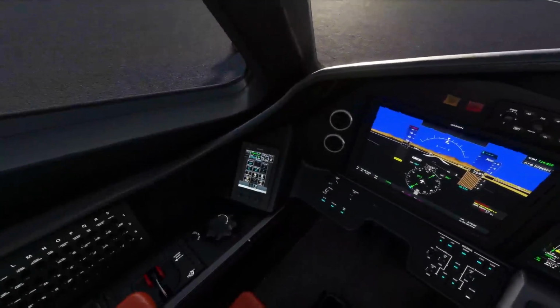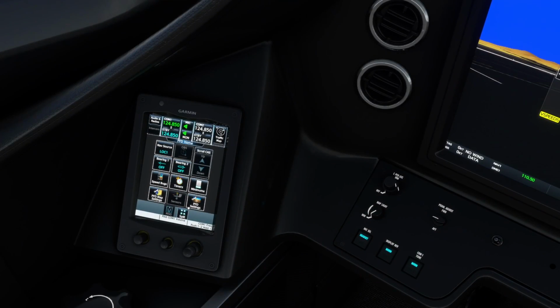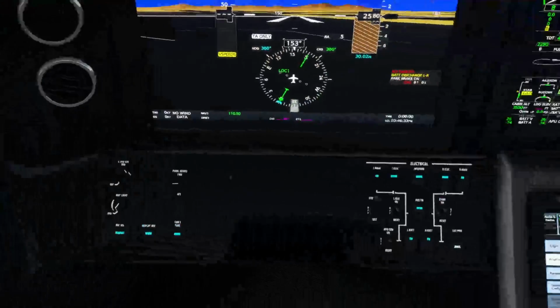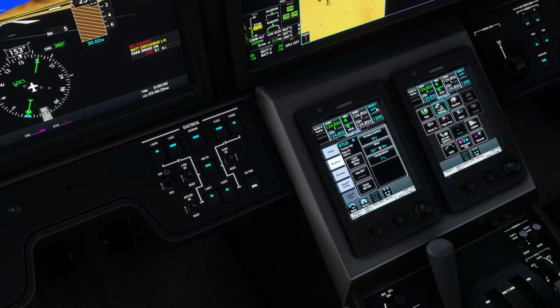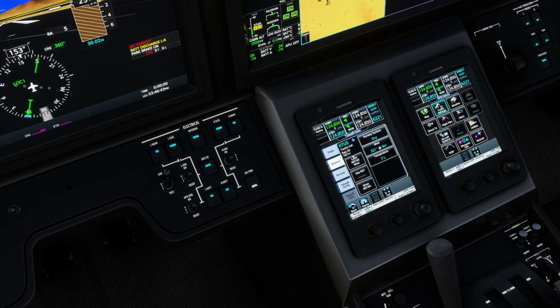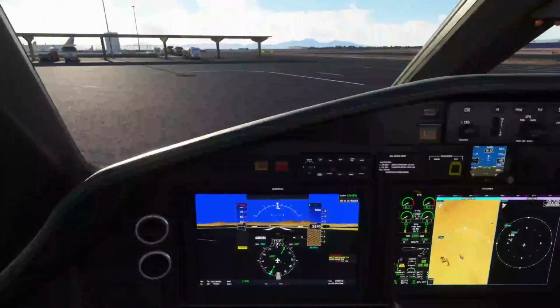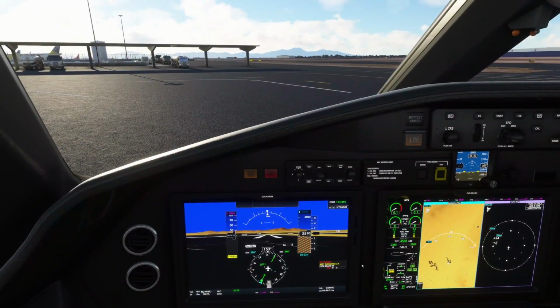Let's go ahead and simulate some clearance. So let's come down and set our transponder code. Actually, you know what? It is easier to do from the TSC. So there's our transponder. Oops, it is in auto mode. And let's simulate 6221 as our transponder code. And it is in auto mode, so it will automatically rotate based on aircraft conditions. Which makes it pretty handy if you ask me.